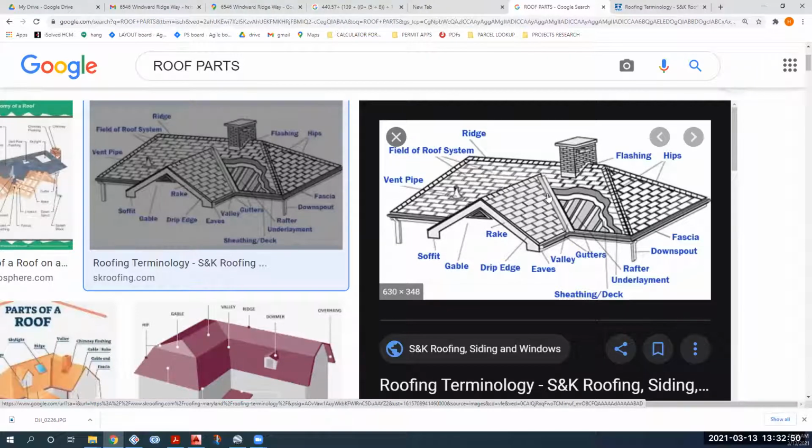So as you can now see, yesterday, Krishna, you were asking what is the difference between the angle from the top and the pitch? So the pitch is this angle, the angle that the roof is sloping on, that we see from the ground. But these angles are always 45. This angle is usually around 8 degrees to around 26, 28 degrees. That's when it's a really steep roof. Typically, it doesn't go more than that.